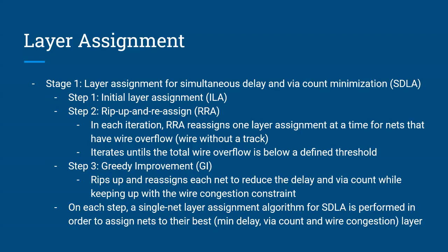Greedy improvement is step 3. It rips up, and this is where they transform the 2D assignment back to 3D, and then reduce the delay and via count there. In each of the steps, a single net layer assignment algorithm for SDLA is performed, in order to assign nets to their best layer.